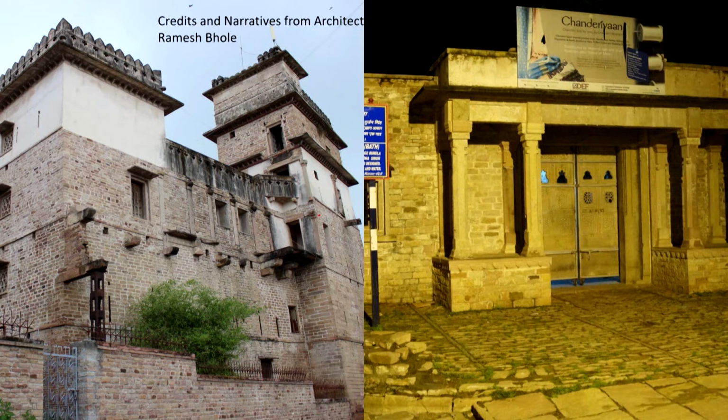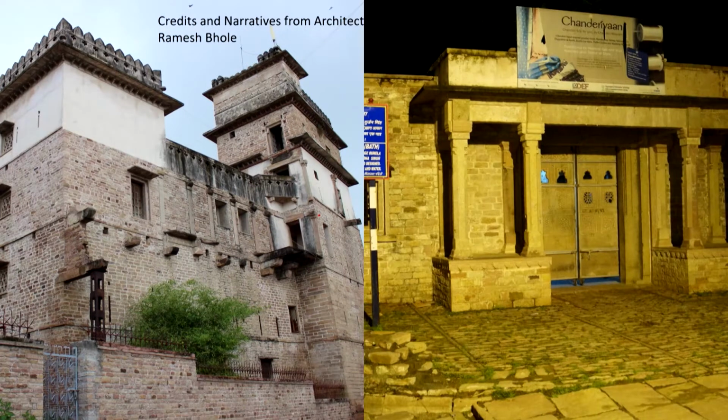In the same place, in the Chanderi Raja Rani Mahal, architect Ramesh Bole, when he was working with INTACH, worked on the conservation of this Raja Rani Mahal, and he explained to us the difficulties in the conservation process, especially with the recent building codes, which do not match the historic elements. For example, for the staircase, how we have to keep it, what height we have to keep. So there are always challenges with the present code and the conservation process.